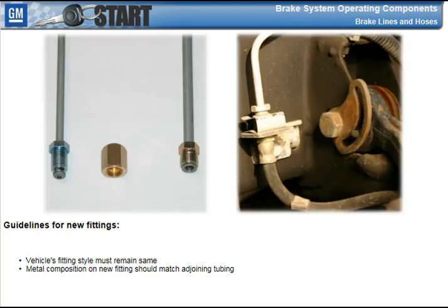There are specific guidelines that you need to follow for installing new brake fittings. Most importantly, when you're installing a new fitting, never change the vehicle's original fitting style. Also, the metal composition of the new fitting should exactly match the tubing to which it's to be joined.